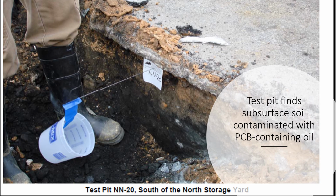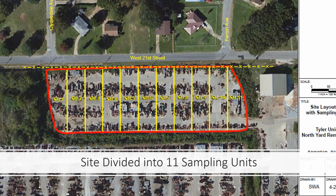At another site with PCB contaminated soils, incremental sampling techniques were used to develop a refined estimate for soil disposal. A test pit showed that soil beneath a parking lot slab was contaminated with visibly contaminated PCB containing oil. In this case, the site was divided into 11 sampling units. A decision was going to be made about the soil underneath the entire slab, but each sampling unit was going to provide additional information that would inform that overall decision for all of the soil.